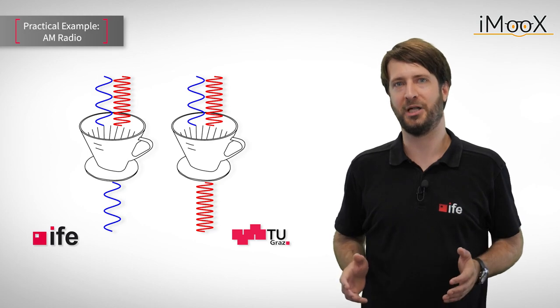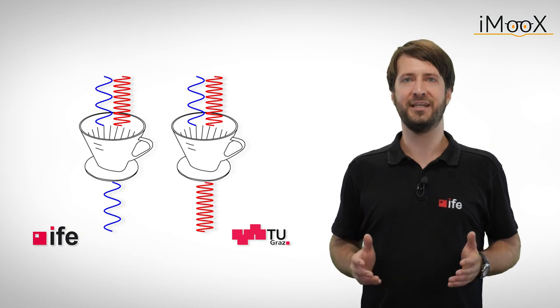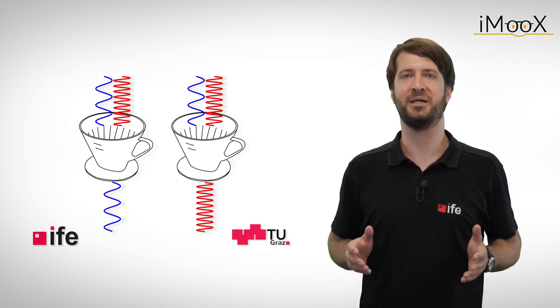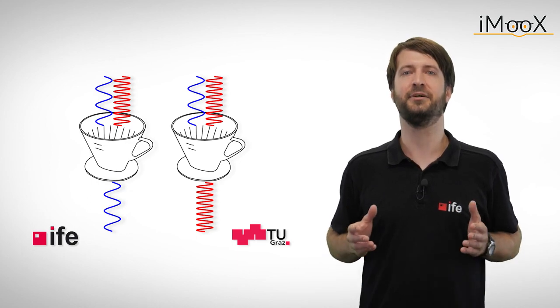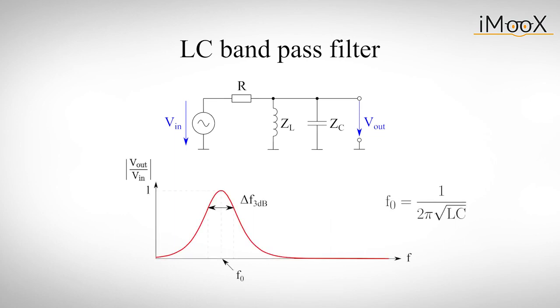Loudspeakers and switched mode power supplies are not the only real-world application of passive filters. Another more outdated but refreshingly simple application of passive filters is the AM receiver of a car radio. If we connect a capacitor and an inductor in parallel, we get the so-called bandpass filter. The frequency response shows us its behavior. In practice, losses in the inductor will again limit the sharpness of the peak around the resonance frequency. We can use the passband of such a filter to demodulate an amplitude-modulated signal.